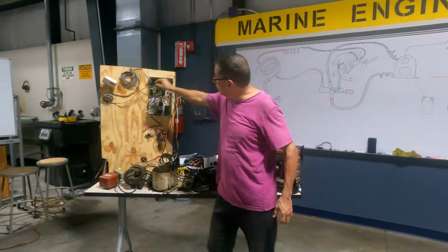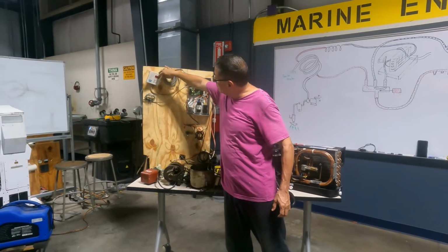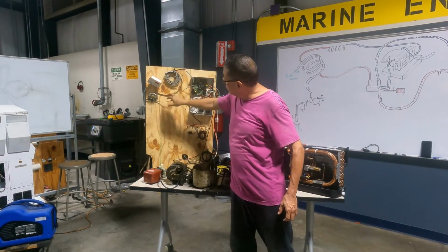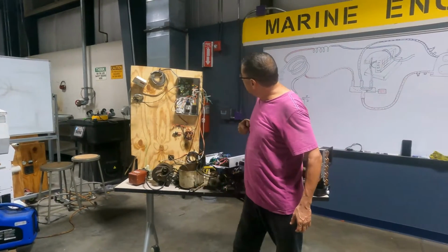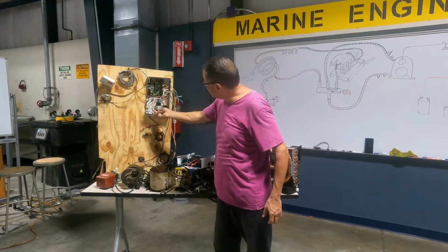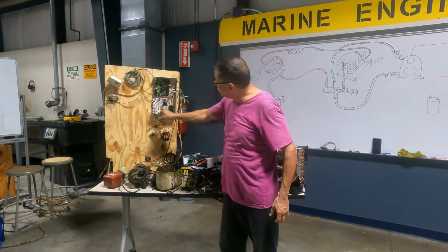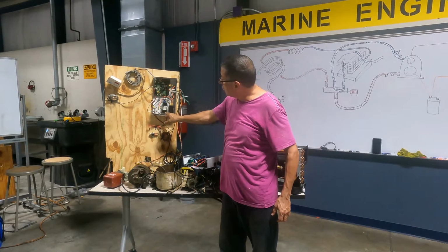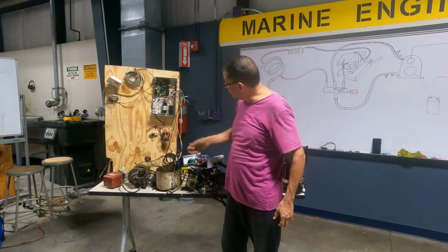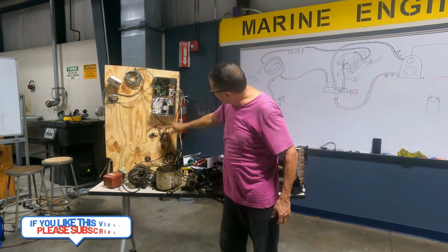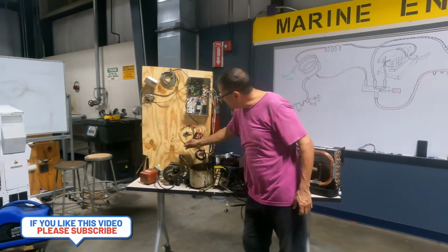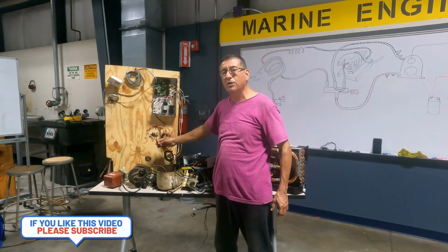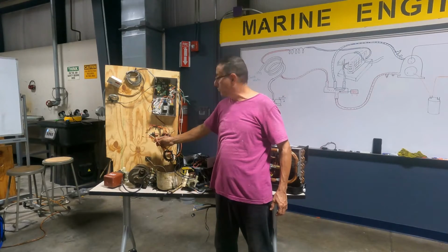Look at the circuit board. This is the thermostat, and this is the connection for the sensor here, both of them. And this is the relay. This is the system relay. This is the run capacitor. This is the start capacitor. From the computer, you have signal for the high pressure switch and low pressure switch. And finally, you have the power for the relay of the motor.